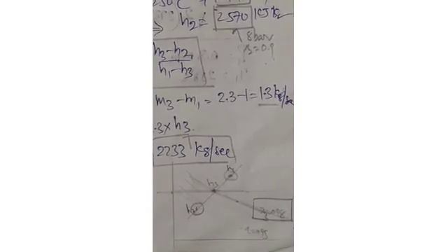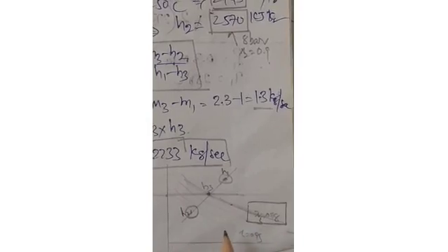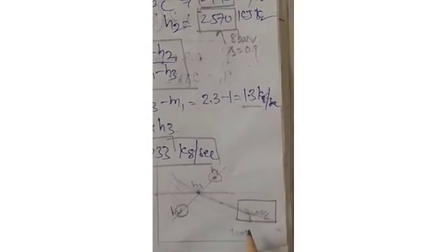So now we have found the first part of the problem, that is, what is the condition of the steam after adiabatic mixing. The condition of the steam after adiabatic mixing is 0.98 dryness fraction. That is the first answer. Now let's go to the second part of the problem, that is, we have to find the velocity at the exit of the nozzle. How to find that: we have an equation